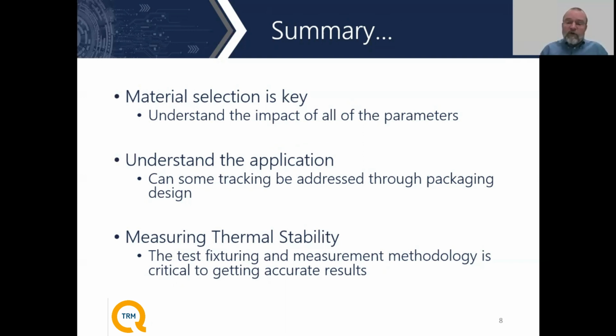And the other thing also is being able to measure it. You have to have enough tooling and fixturing in place to be able to accurately measure just the unit, and remove the entire test setup, including cables, from that measurement, so that you're not fooling yourself into thinking that you have a good solution. Cables can make things look worse.